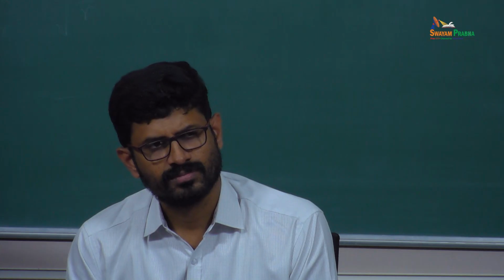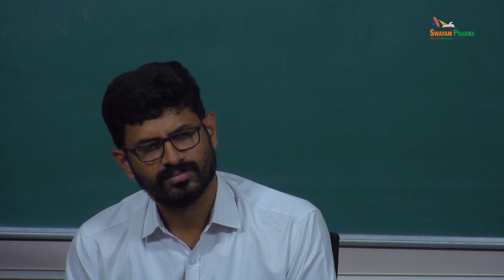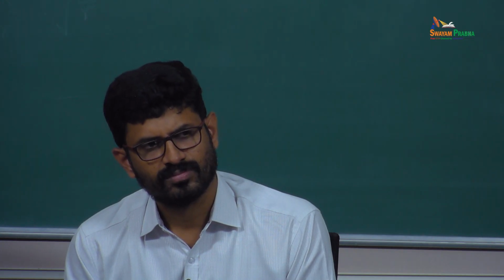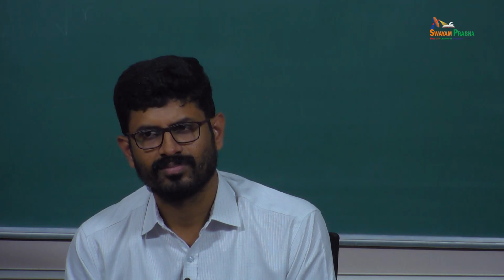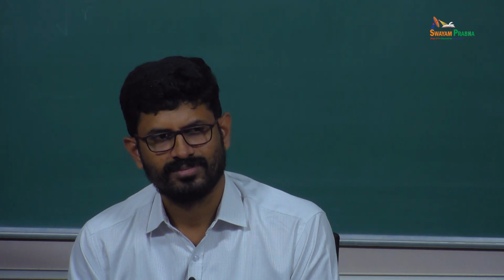Yes, Prof. I could give you some numbers. Some literature said that moorings cost about 40% of wave energy converters. And in 2019, I visited Hawaii. There's a wave energy test site. Some moorings failed, and they are in the process of repairing and rebuilding them. The water depth is not that deep, from 30 to 80 meters, I don't know which one failed. It takes them $2 million US dollars. So that gives you a sense of how much it costs.